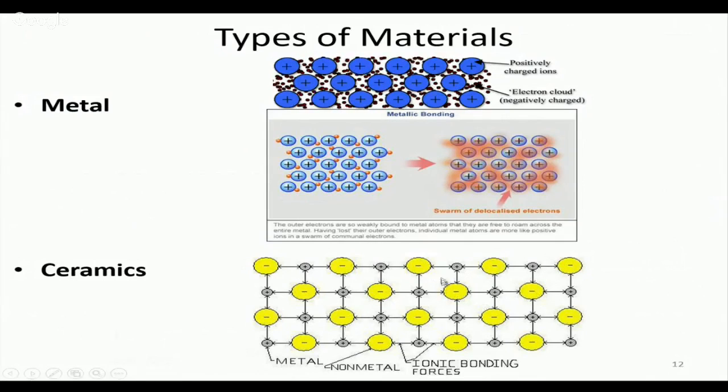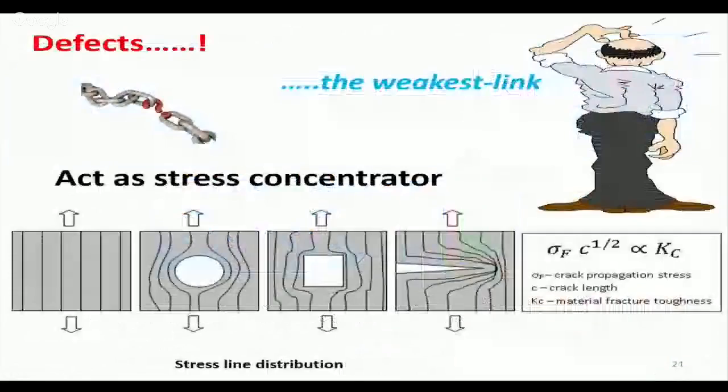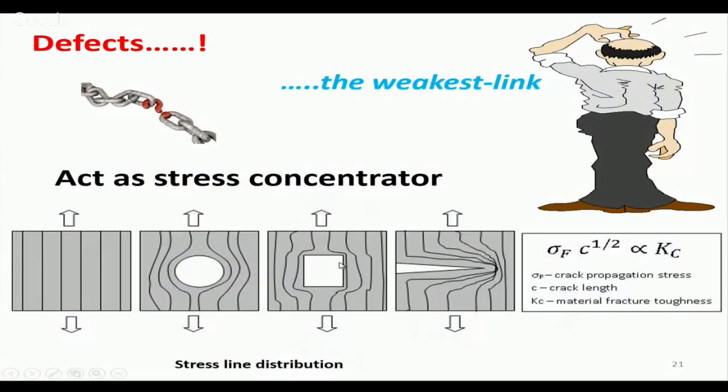So that is why they break, because there is no slippage and this notch remains forever. There is no scope for this notch to be rounded, and that is why ceramics always behave like a brittle material, and metals, even if they have the notch, it will be rounded, and that is how metals have plastic deformation, and ceramics will not have plastic deformation, and they will be brittle.